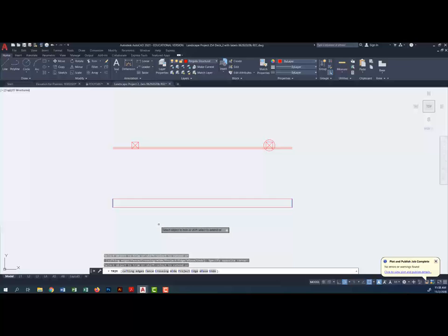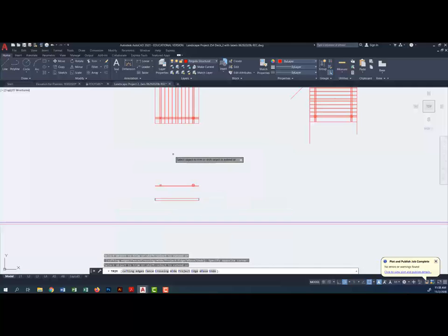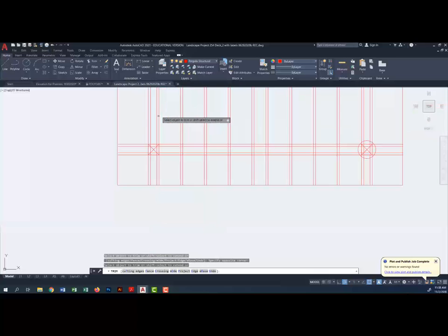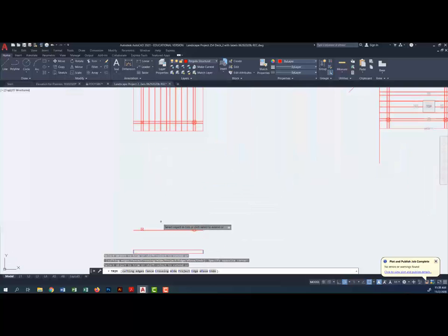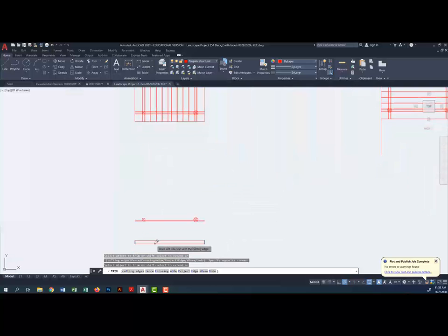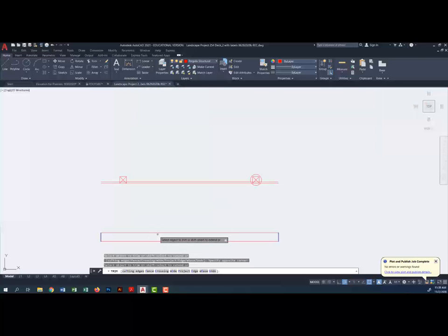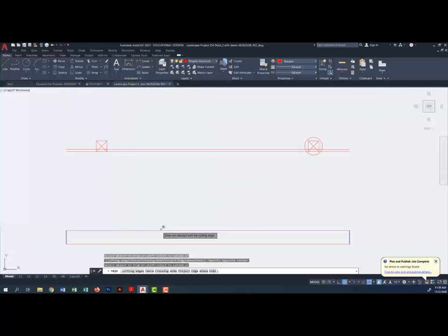And that is the side view of the actual lintel that's coming down. Now I'm going to draw the end views. The end views, I'm going to use the information I have here. Forgot to mention, in my particular case, what I'm going to do is have a 2-inch recess or notch in the actual ceiling joist. So I'm going to offset this now 2 inches, so I know how far down to bring these.